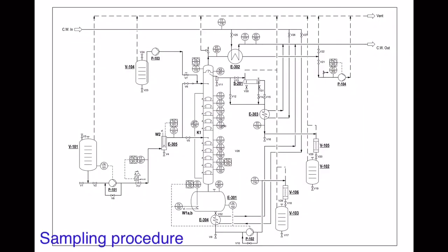Now we proceed with the sampling procedure. I will show you the precaution step before starting the heating process. First thing first, you have to make sure all the remaining liquid in the sampling valves, which refer to V9, V11 as well as V16, is removed.